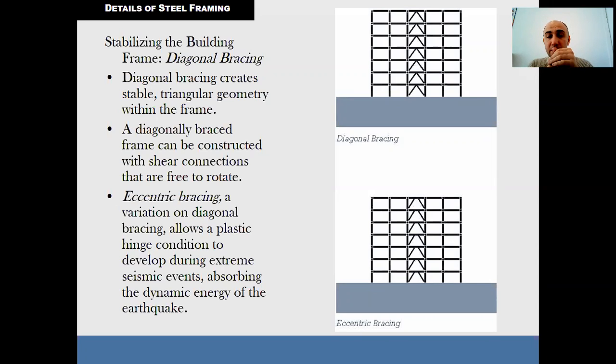But if there are lateral loads, the importance of using the braced frame is higher. The positioning of the braces, however, can be problematic as they can conflict with the design of the facade and the position of openings. All of them increase the difficulty of design.